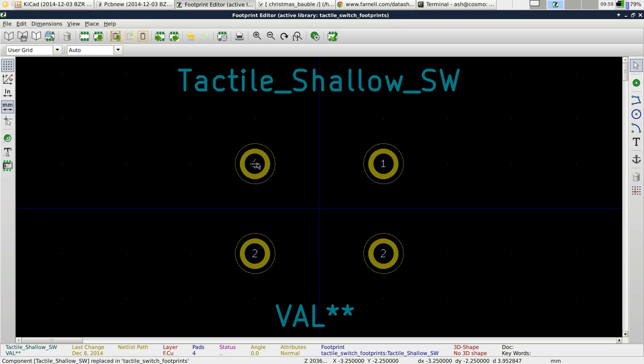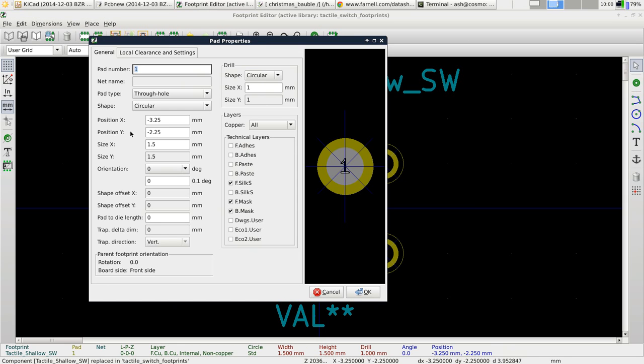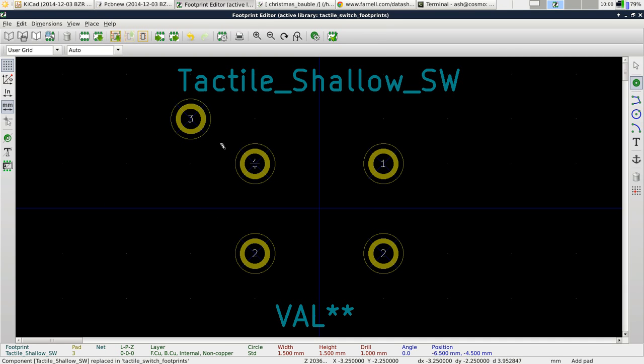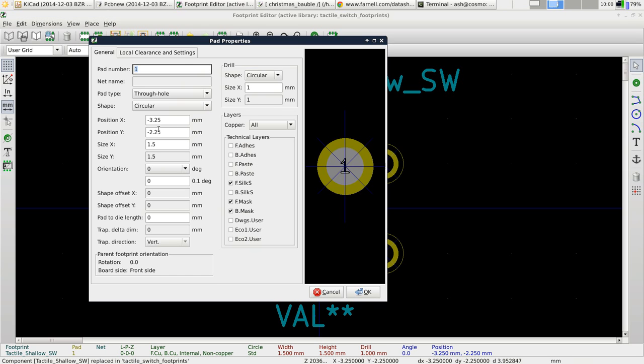Or if you can't do that, you can usually always do that, but sometimes it might be more convenient, like you know that something is near to this pin, there's one over here for example that is relative to that pin or in a strange position, and you don't want to change the grid. You could just, because you can change the X and Y positions just here, like I could add an extra one in here for example, and if I knew it had an offset relative to there, I could just look at this, add on to this what the offset is, and just manually change the position there.